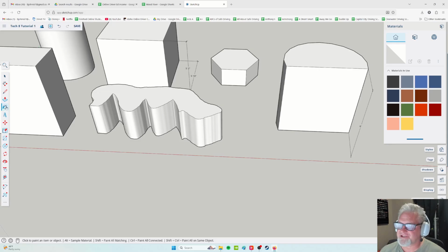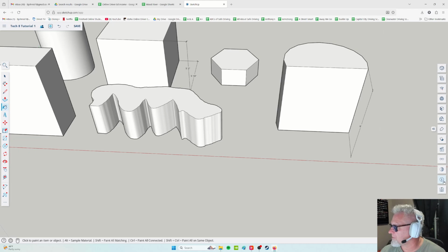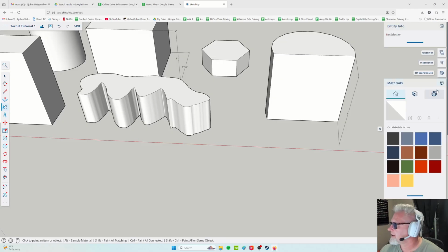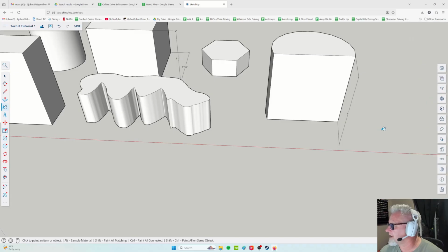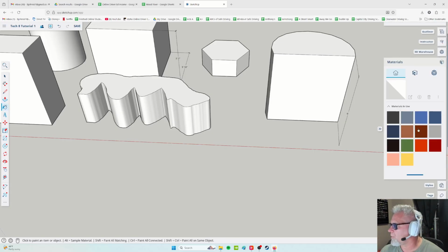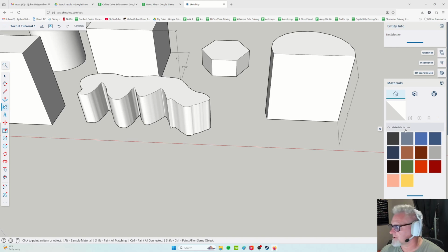Click. Now this tool actually opens up options on the right side where I was before with model information. This is called the options toolbar. So if you close it like I just did and you wonder, well, wait, how do I find the colors, the paint? Where is it exactly? You can roll your mouse over things and see. Here's one that says materials. That could be it. It is. And if you're not sure, you can always go back to the paint bucket. Bink, it just brings up the materials. So let me explain how to find all the colors and materials.